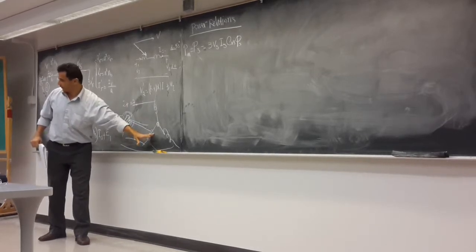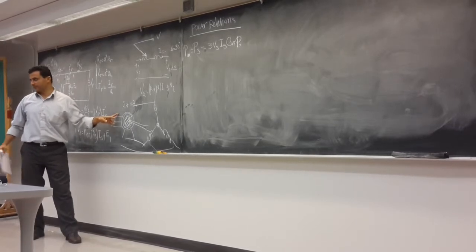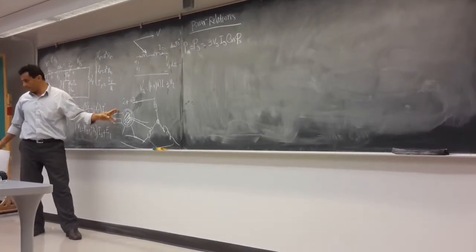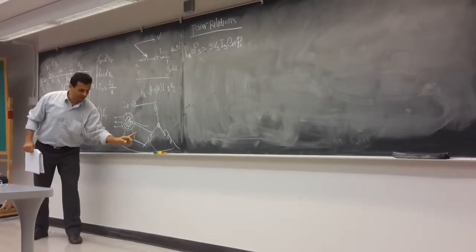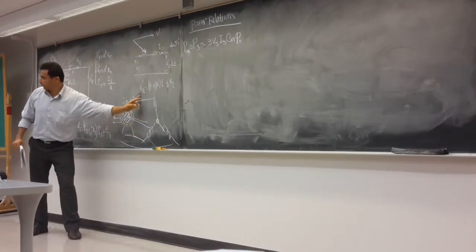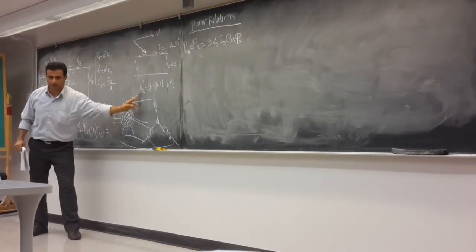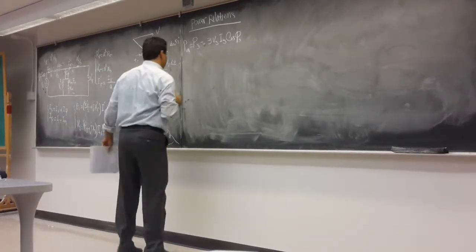In a star connection, this current, which is IL, is still I phase, right? I phase and IL in the star connection are the same. But if we give you VL, V phase is going to be VL over the square root of 3, right? That's the three-phase system we went through. So this is the P in.